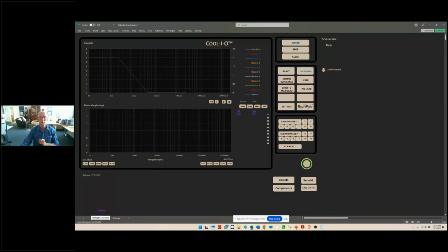Sweep initiated. So now we're doing the exact same thing that LTspice was doing, which is injecting a signal into the loop, but now we're injecting into the hardware. So you can see the count of the sweep here. And it's going along. It's always a little bit noisy down at low frequencies, but the phase scale, notice that's only a 1 degree phase scale. So that's actually quite clean. And we can see our loop, not our loop, this is our power stage transfer function coming in for the converter.